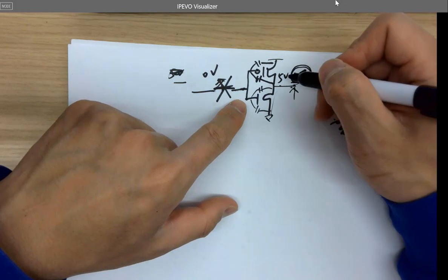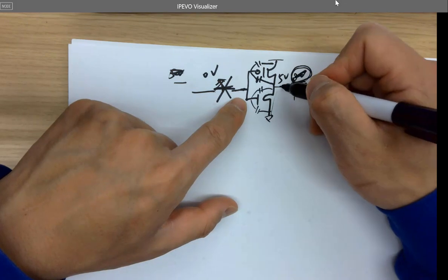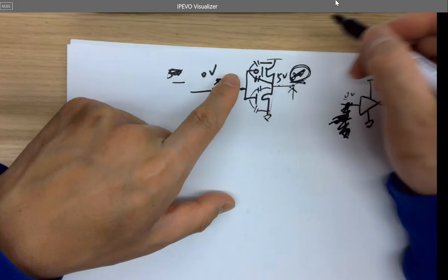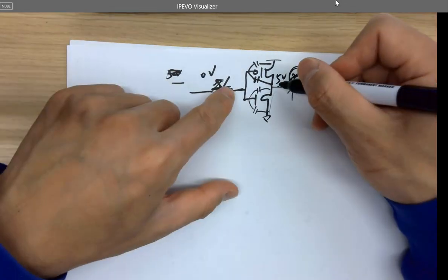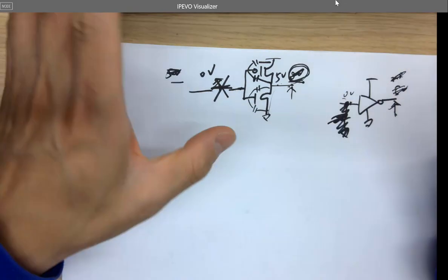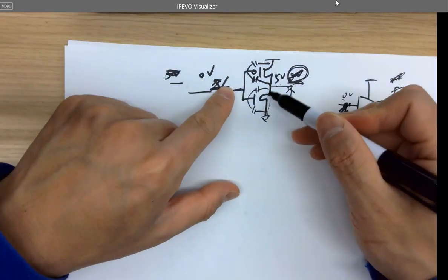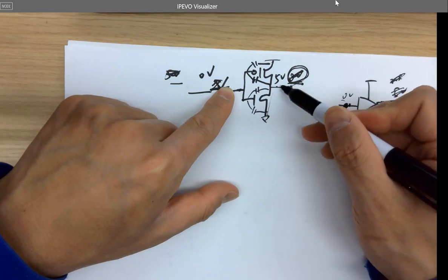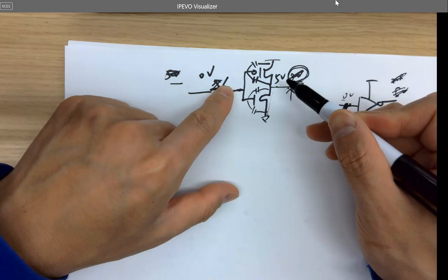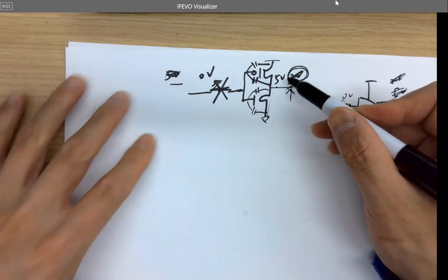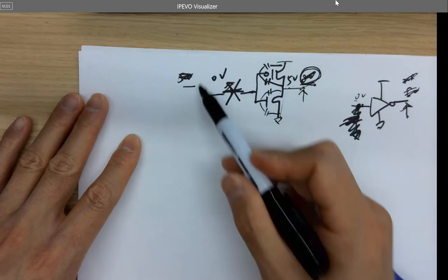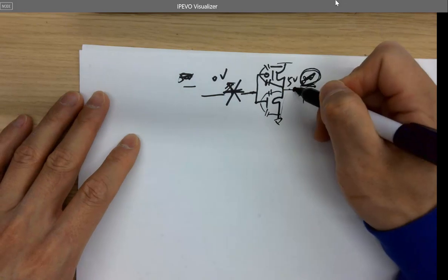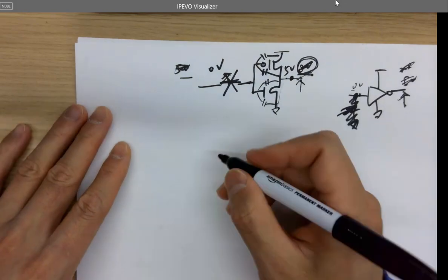That is right. It's going to hold it for a little bit. Eventually, it will be discharged to the environment, to anywhere on the circuit, wherever this is plugged into, or the air, or anywhere, it will be dissipated. And also, the transistors are not perfect, so it's going to leak current to the ground. So eventually, this will become unpredictable as well. Which means if you have just an inverter, this point won't be able to store that voltage forever. So what if you have this circuit?